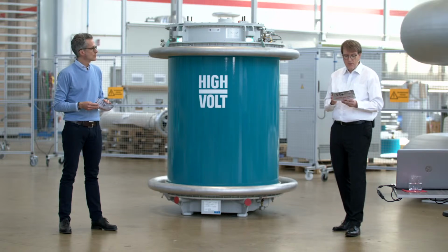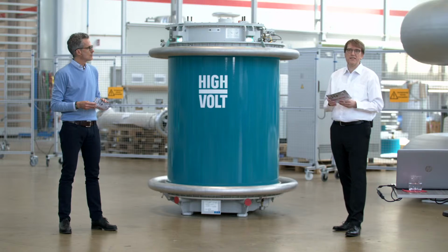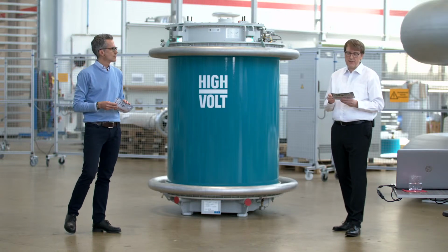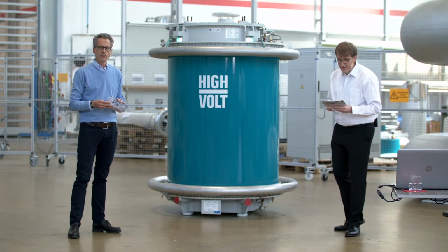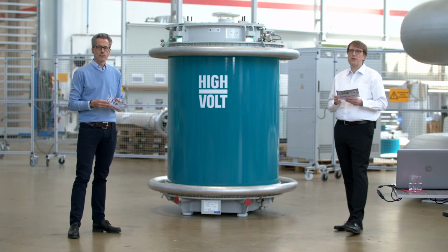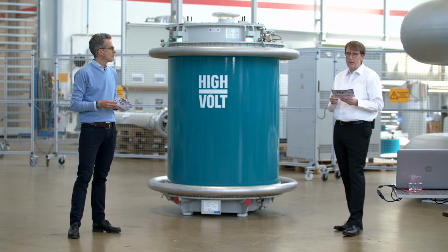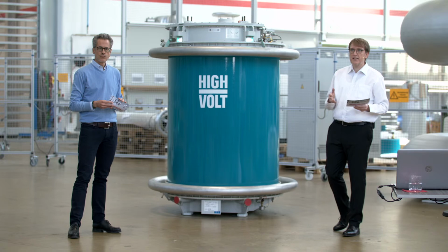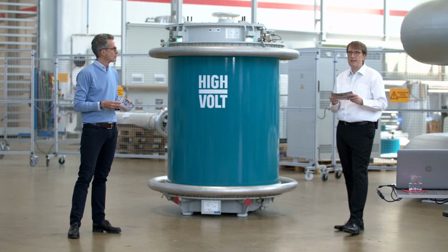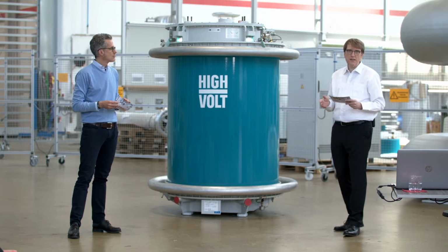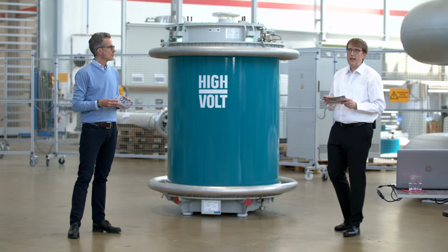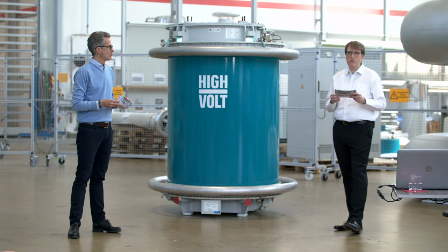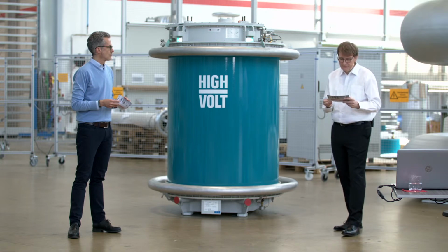We know that monitoring is something always requested from the operator of such cable systems. In such a monitoring system, partial discharge measurement seems to be one crucial element. Nevertheless, DC partial discharges, we have discussed that already last year. That's something where conventional technologies have their limitations. And today we would like to discuss also completely new ways to handle that topic.